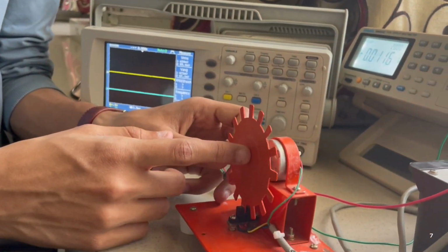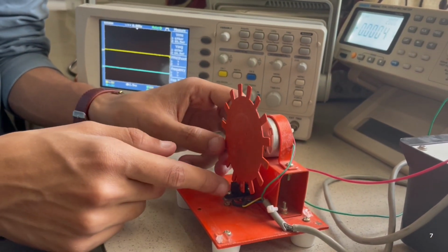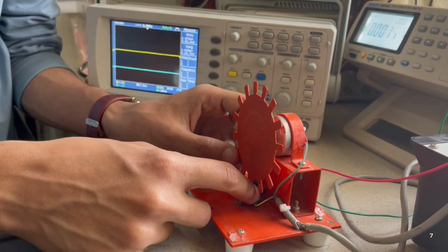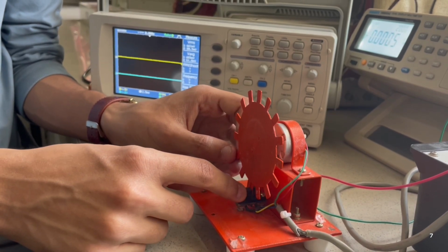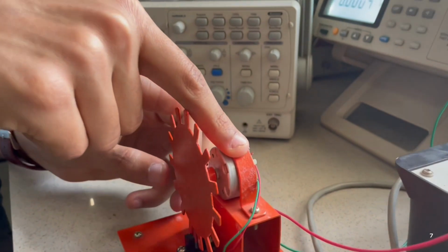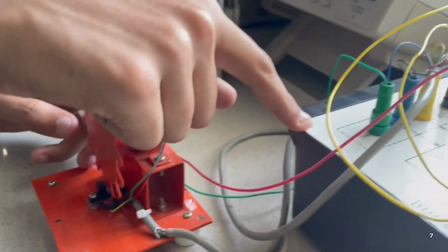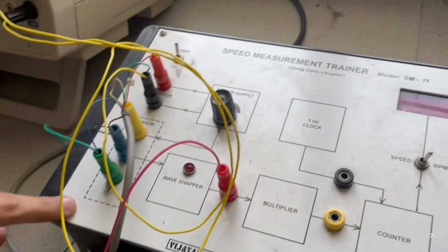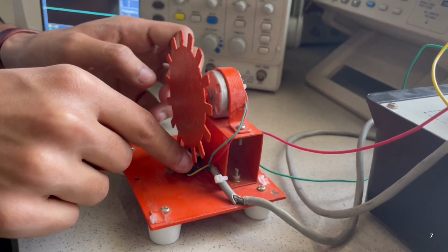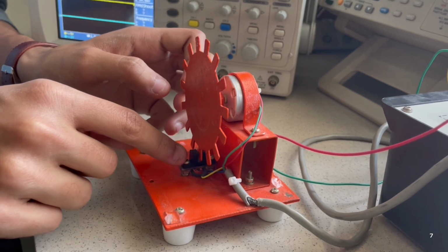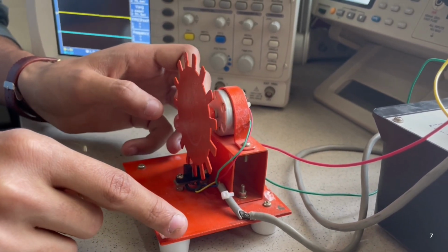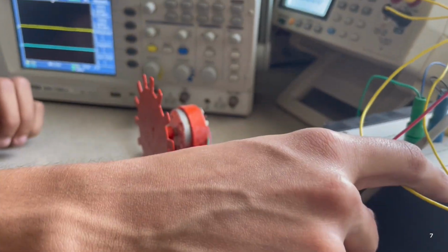Now we'll be discussing the instrumentation setup here. So this instrument consists of a rotating wheel with 15 spikes. It also contains the optical sensor here. This is the light emitting diode, and this is the optical sensor, which basically detects any kind of electron or photon that is coming from this light emitting diode. And it also contains the DC motor connected with the circuitry here. So what usually happens is a voltage is provided from the circuit to the DC motor, which turns this rotating wheel. Whenever there is an obstruction between the optical sensor and the light emitting diode, current is not generated, which is detected by the experimental setup.